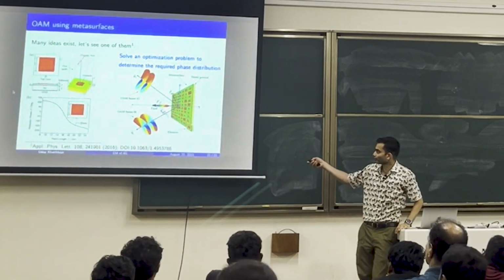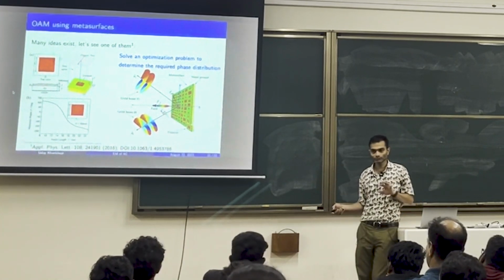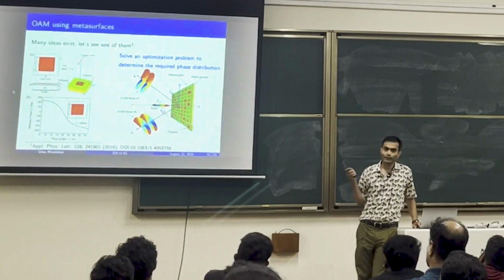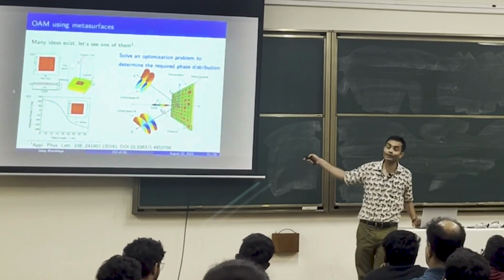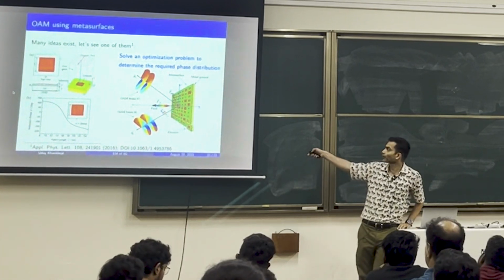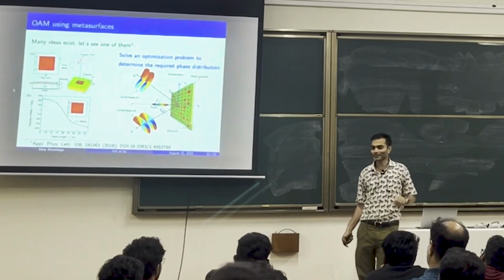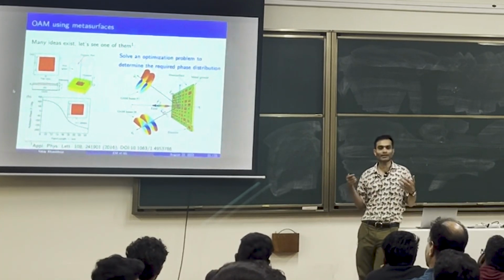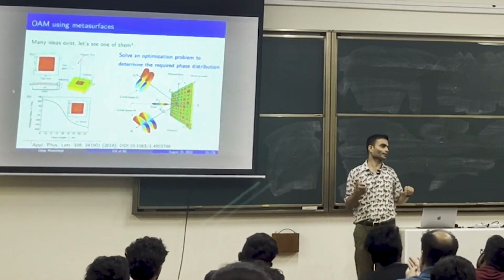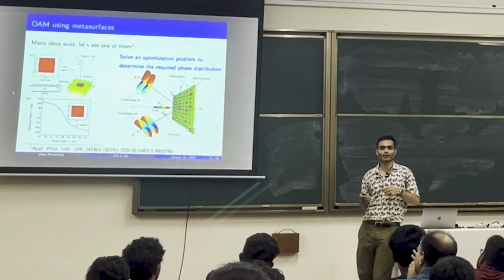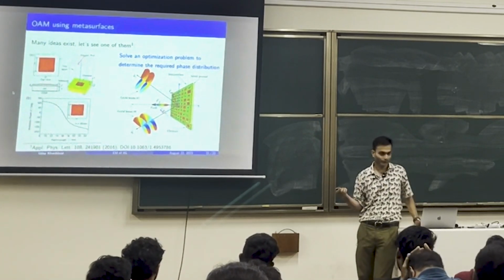So you can see the input feed is a plane wave, and out are coming beam 1 and beam k and so on. This is possible. But that will be fixed. This will be fixed, right? Unless I put a diode in each one of these elements. He's already doing this. But if you want a dynamic metasurface, that's what you'll have to do, right? So these are a few of the tricks of the trade. Put in a few RF switches, diodes, whatever. You can make the beam do all sorts of things you want, right?